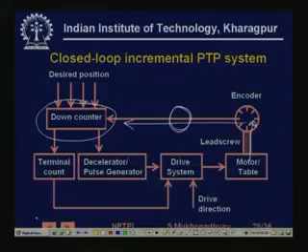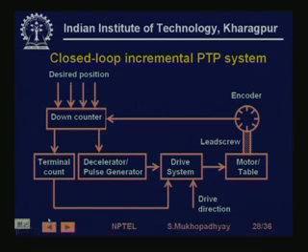Previously, every time a pulse was given to the motor, the counter was being decremented on the assumption that if a pulse is given to the motor, then the table will move. That assumption is not here. So this is the basic difference, otherwise they are the same, and you can drive it a little bit faster and with a little bit higher loads. Even if loads vary and there is some problem, at least the counter will not be decremented.